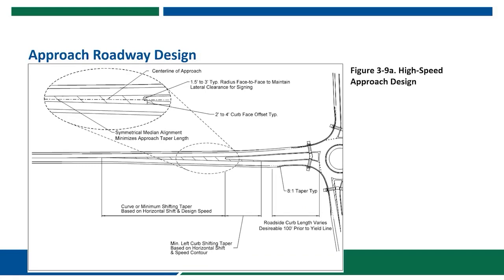Stopping sight distance should be preserved when adding reverse curvature, and this is necessary both horizontally and vertically. You may have seen chicanes that were a little overdone with extensive reversing curvature, and the forward sight distance of the road is actually cut off by the splitter island on the approach. We're looking to use gentler chicanes so that we can maintain that forward sight distance to the entry line.